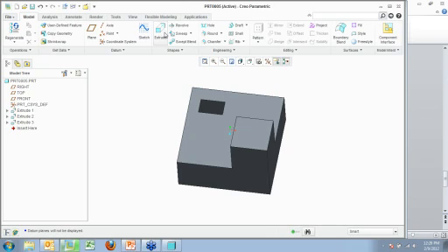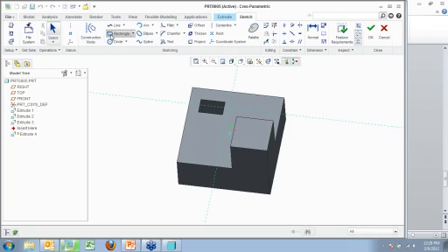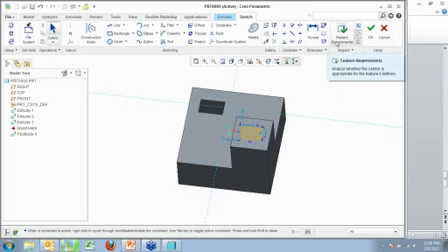So let's hop back in. We'll do another extrude right here on top of this, just to show you some Sketcher stuff here. So you noticed when I completed something, and this isn't a new feature by any means, it's shaded by default. That is on by default in Creo Parametric. That was an option in Wildfire 5 and maybe, I believe, Wildfire 4 before that. You have your feature requirements, shade closed loops, highlight open ends, and overlapping geometry, which when these two, shade closed loops and highlight open ends, are turned on by default now.